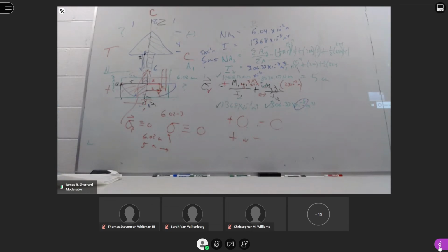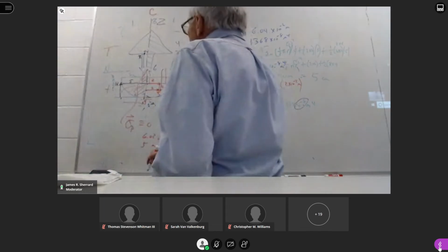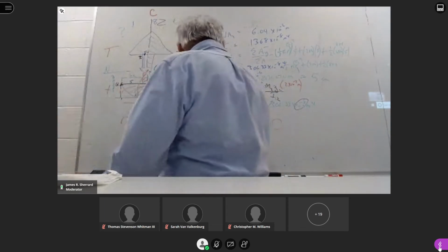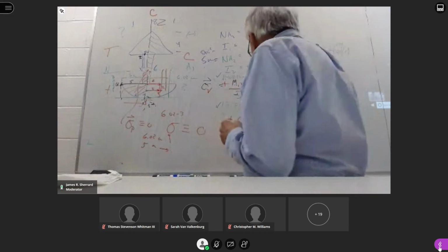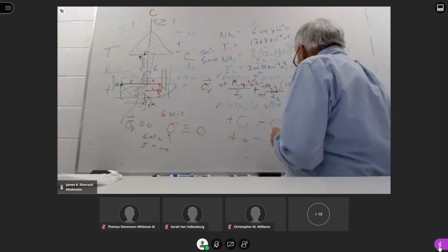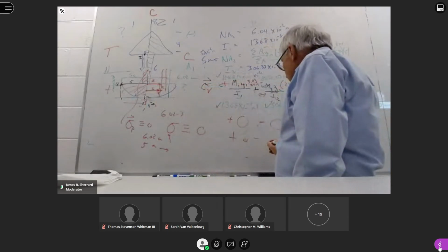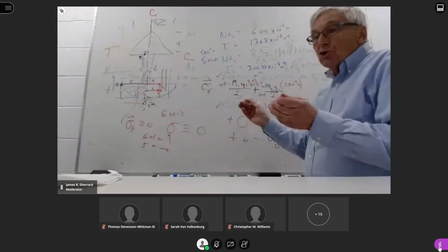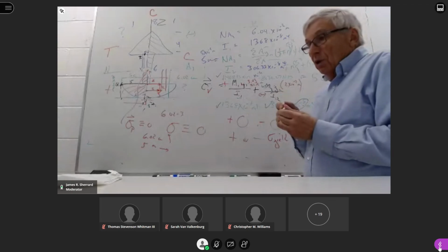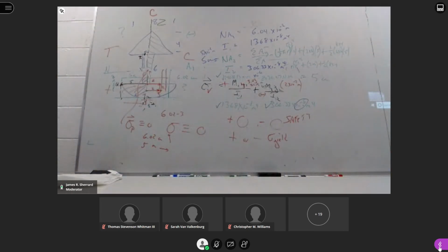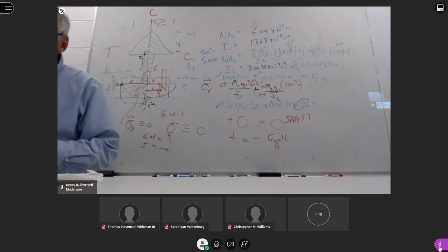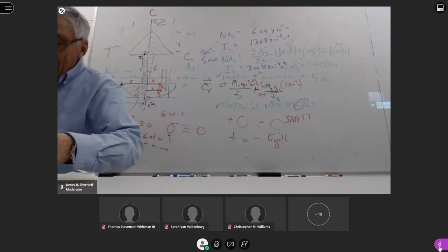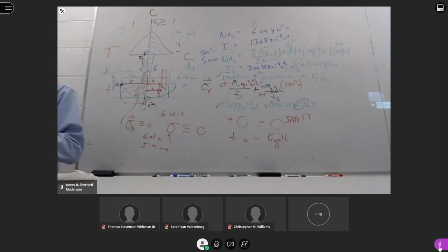The only other thing we talked about was, whenever you calculate this value, whether you did it for R or Q or V or whatever, we can always go back and look at safety by comparing the stress at any point versus the yield for the material. Notice in this case, I never told you what the material was. Did anybody try to do the extra credit?